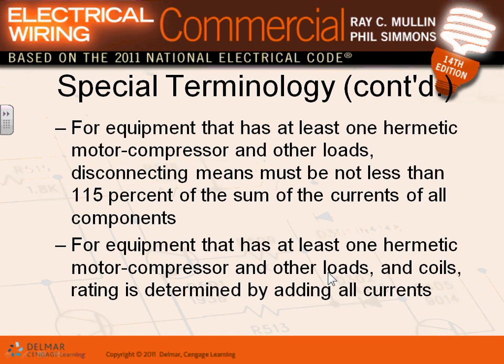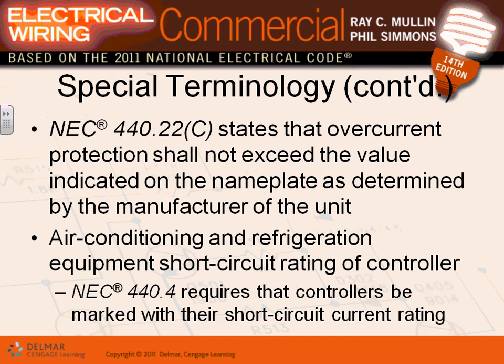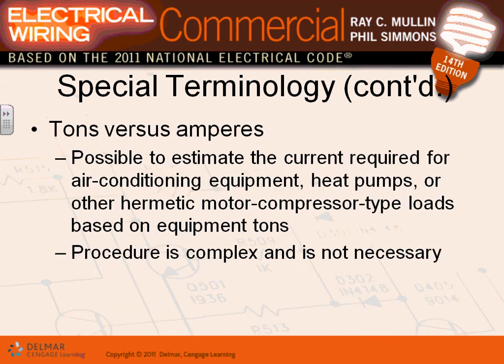Okay, special equipment. All right, terminologies. Controllers, all these controllers, guys, we don't get involved too much in sizing them. Packaged units are sized in tons versus amps. For rooftop units, say 50 or 100 tons, there are tables that translate the tons into kVA or kW.